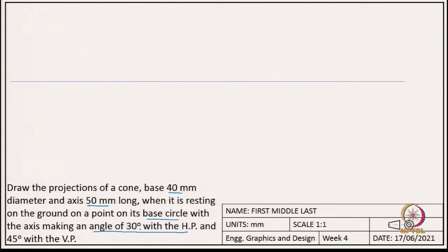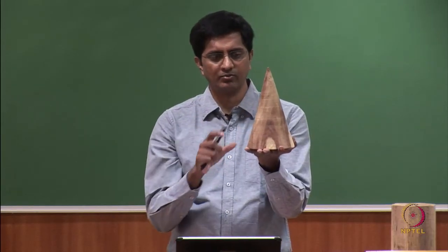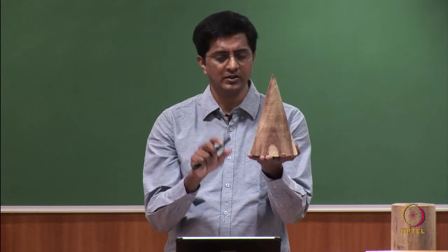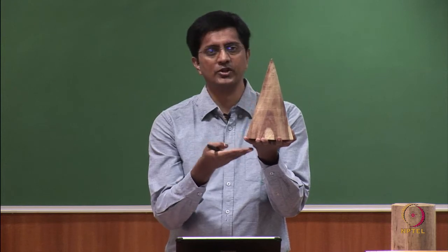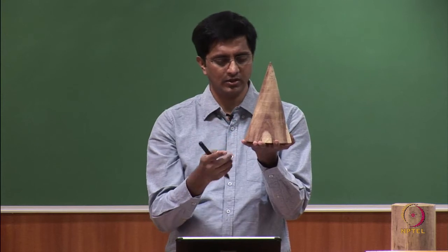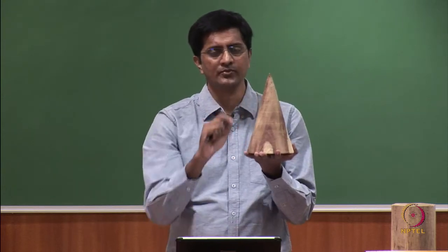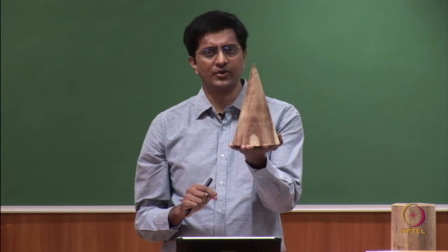We start with the reference line, and of course, again we will break it down into 3 steps. The first step is simply oriented in a very simple manner, which is the base is parallel to the horizontal plane, and the axis is perpendicular to the horizontal plane and parallel to the vertical plane. Okay. So, for this it is easy to capture the front view and the top view.